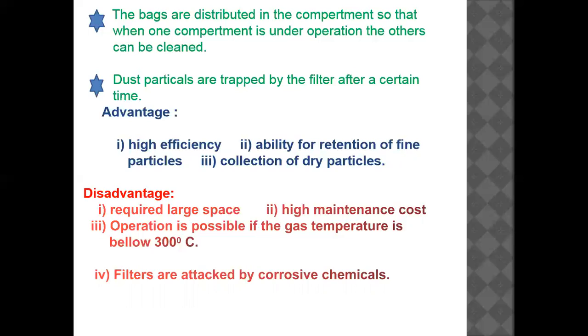Disadvantages are that it requires large space and has high maintenance cost. Operation is possible only if the gas temperature is below 300 degrees centigrade. Filters are attacked by corrosive chemicals.